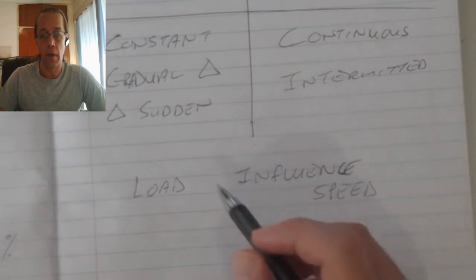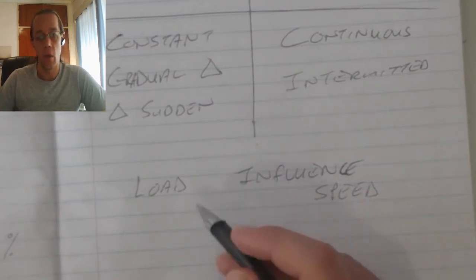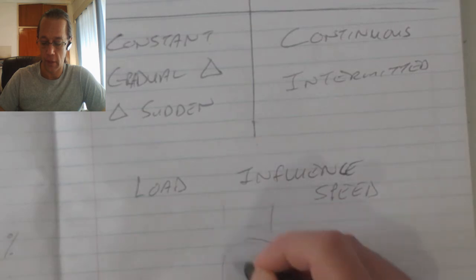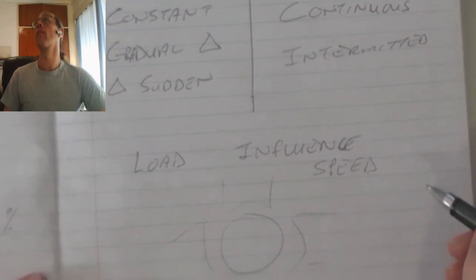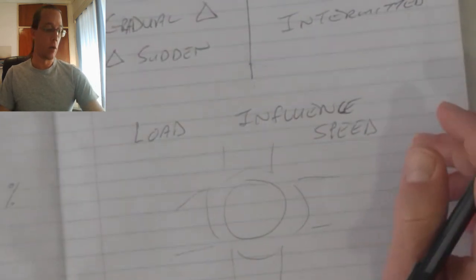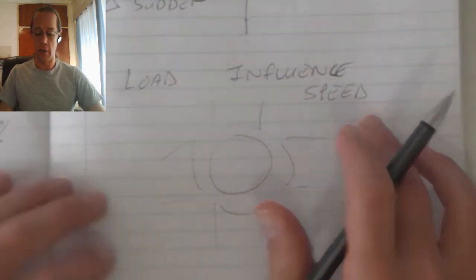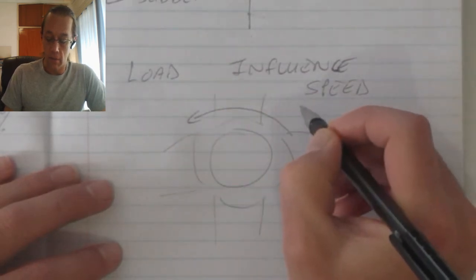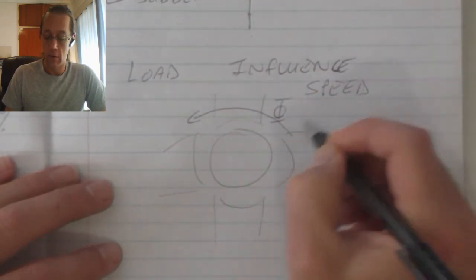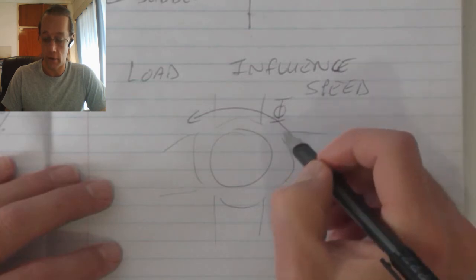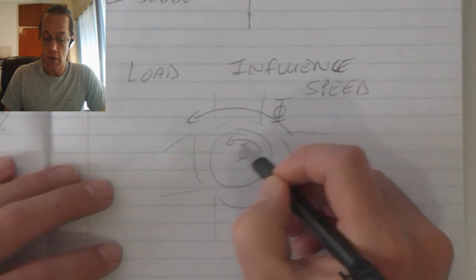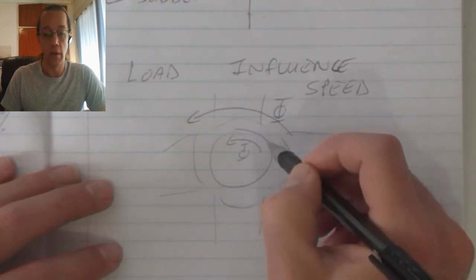Now what happens is, when we place that rotor inside the magnetic field, the rotating magnetic field runs at a certain rate. The rotor rotates slightly slower because of the load.